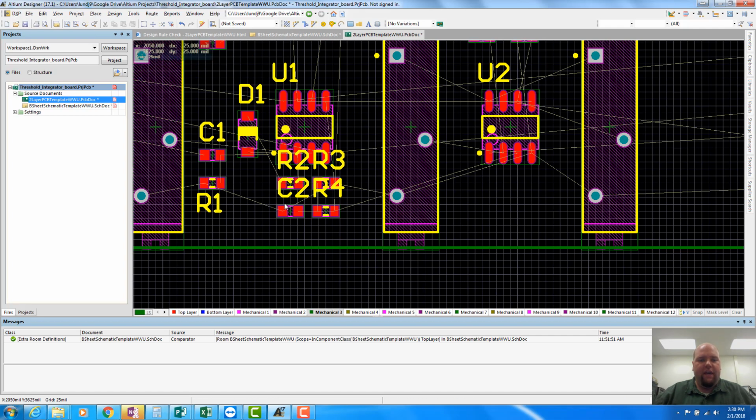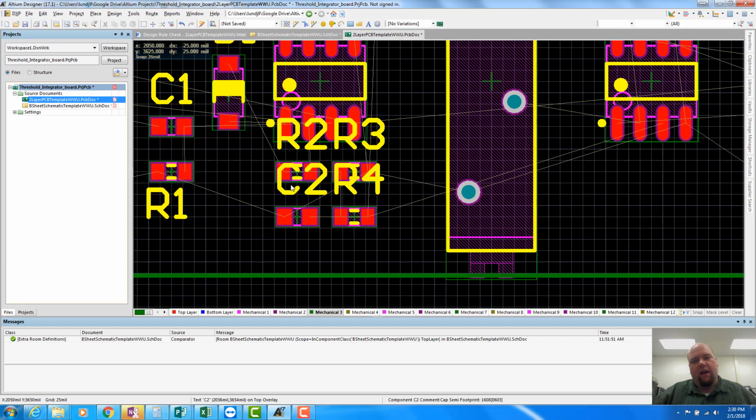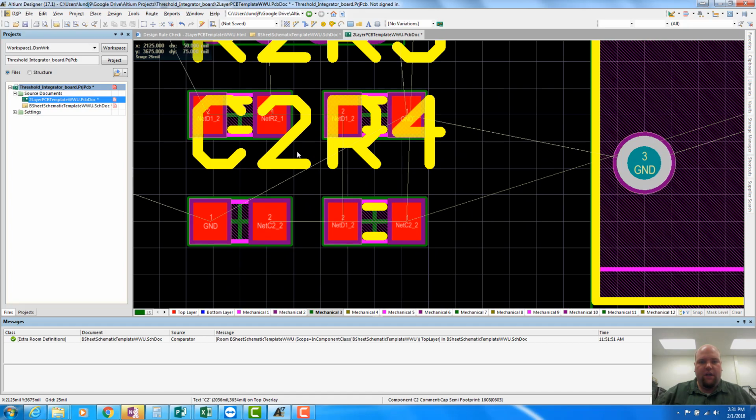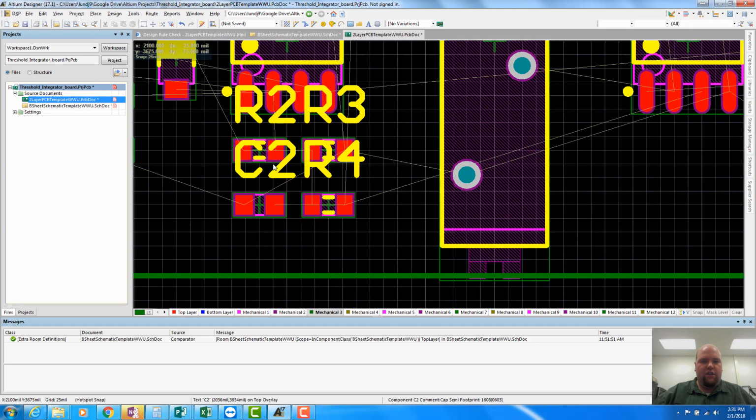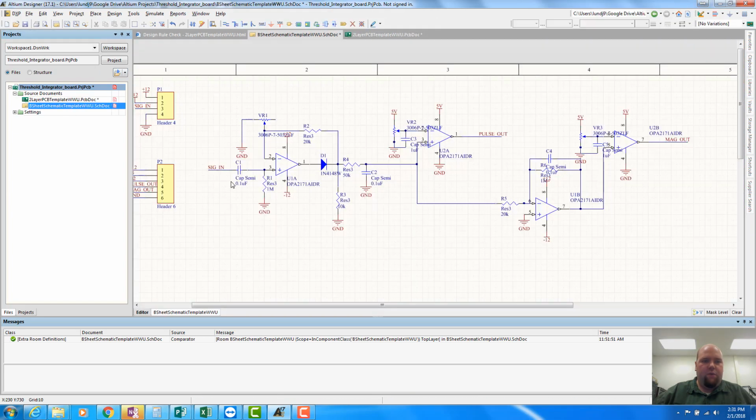So what I'm doing now, and you see this a lot with op amps in particular, quite often you'll have this sort of quad of components when you have RC networks, either in the feedback loop or connected to one of the pins of the op amp. It's very common to have 4 components or so that are all connected there. And it's not always clear exactly what the best orientation is to make sure those stay connected. Usually it's good to just see if you can follow what you have on the schematic.